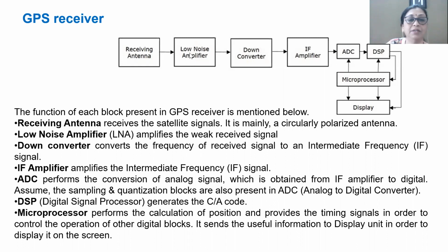Okay. So after this, the received signal has a certain frequency, and that needs to be converted into a frequency of your receiver. This is done by computing the difference between the frequencies, and a single frequency is formed, which is called the intermediate frequency.